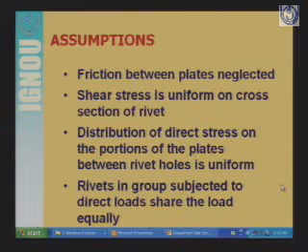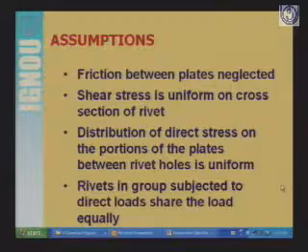Third is distribution of direct stress on the portion of plates between rivet holes is uniform. When we are considering the rivet holes here, then we assume that the distribution of the direct stress is uniform.